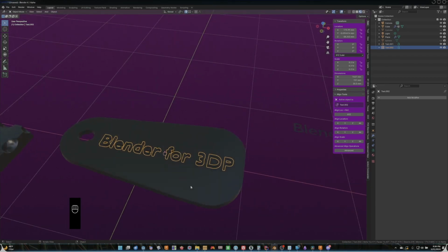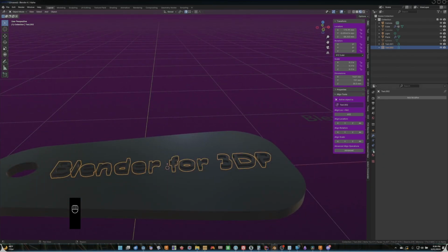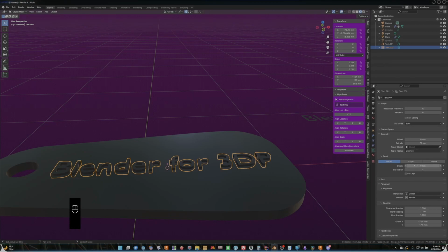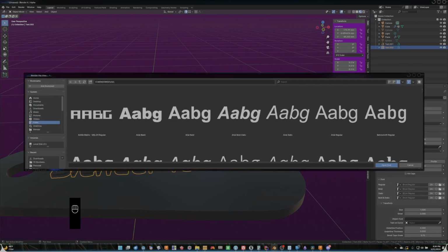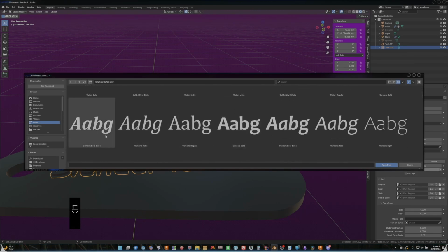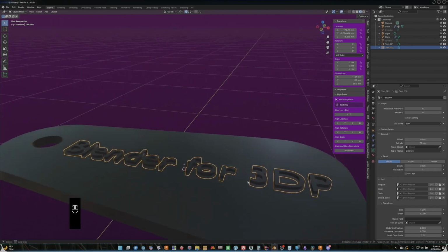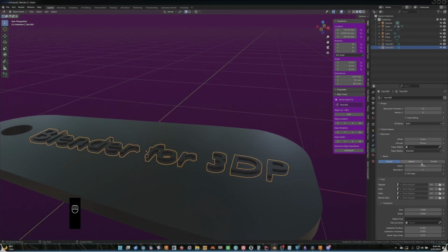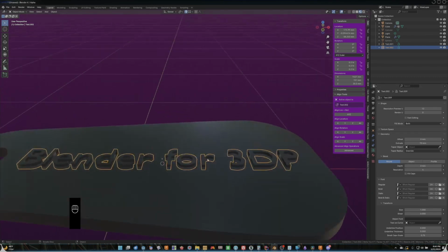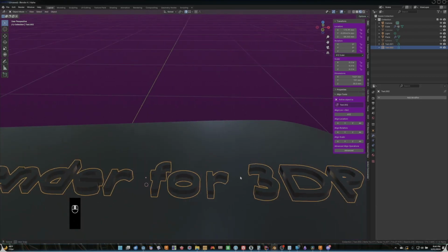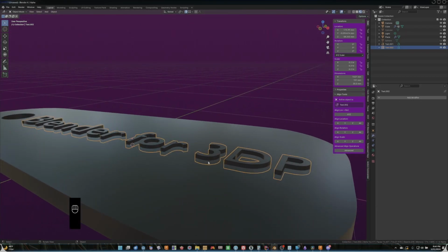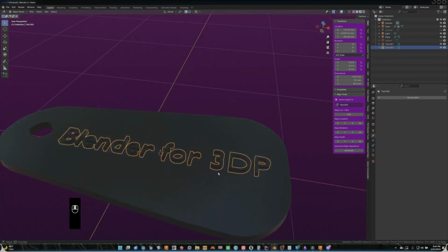Before I do that, I want to caution you about something. You might feel the urge to use the bevel settings. You can change fonts simply by selecting the folder for each of the types and then scrolling through and finding a font that matches that type. Unfortunately, a lot of fonts will create overlap as soon as you try to use your bevel settings. I'm going to recommend against using beveling either here or using the bevel modifier or by filleting. All three options will produce overlapping geometry errors and create a lot of issues.